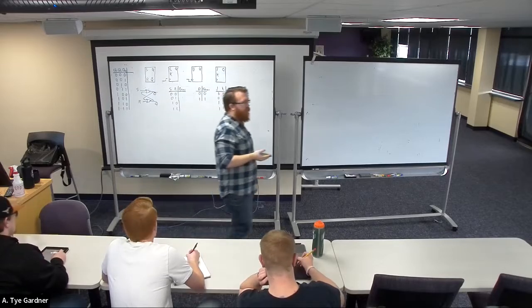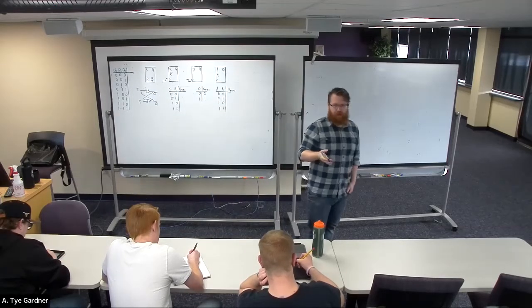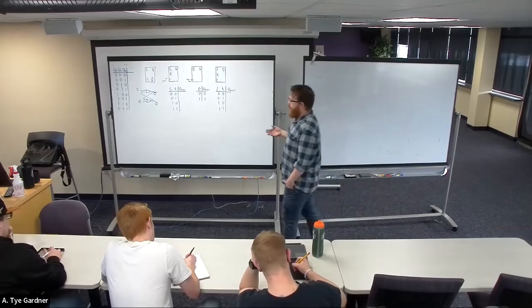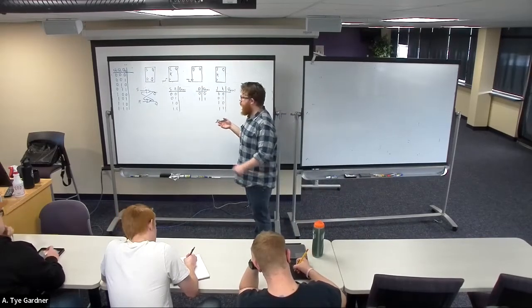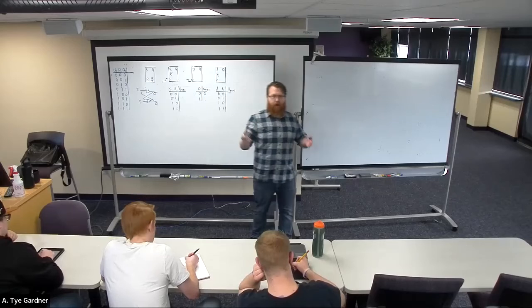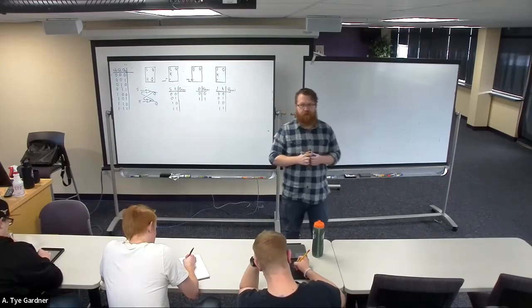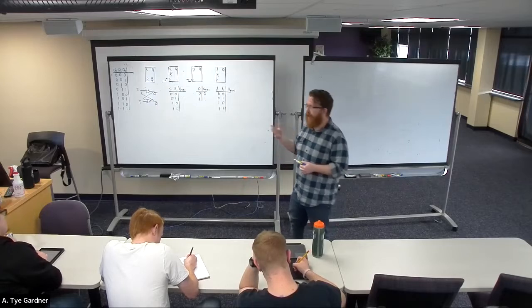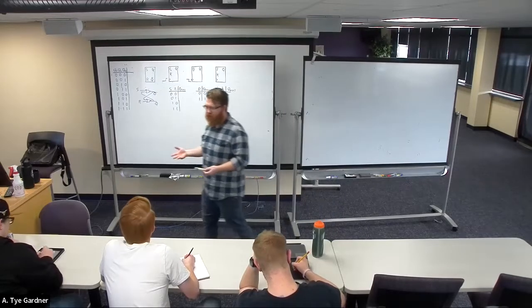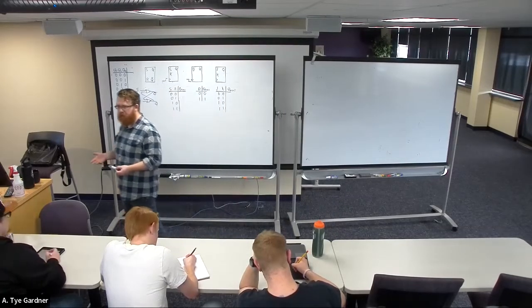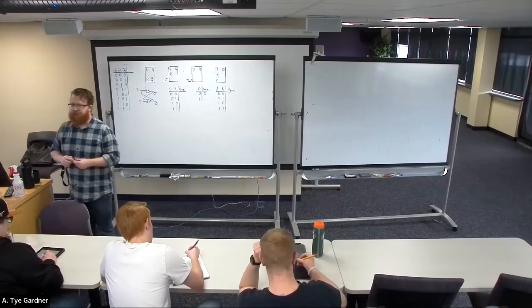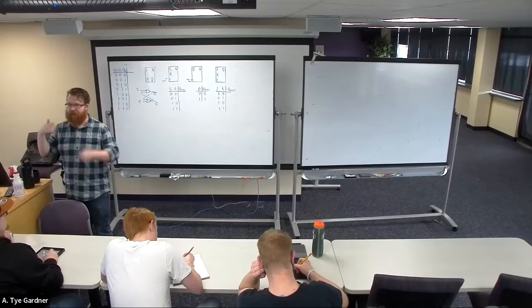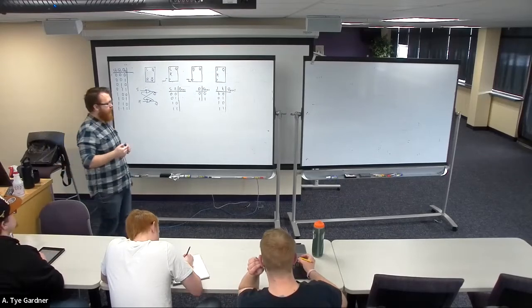And the point of a clock is simply to synchronize commands, to make sure that we're doing things at a known time, at a reliable time. And something that came up in the last lecture that is a good point is: why do we want synchronous? Because it turns out that asynchronous design has some major benefits. It's an active field of research how to design asynchronous circuits, because we can get some performance benefits out of it. But it turns out to be hard because we like to know exactly when things are happening rather than having them happen as fast as they can and see where that gets us, right?